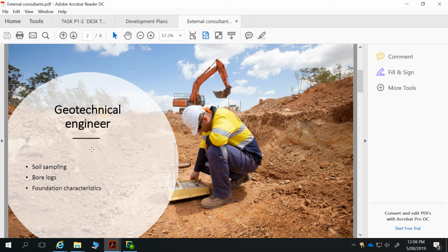If we've got really clayey soils, we're probably going to be dealing with something like about 200 square metres of a dispersal area. That's a massive amount of area to fit into a design. If we've got sandy soils, we might cut that back down to around 150 square metres.